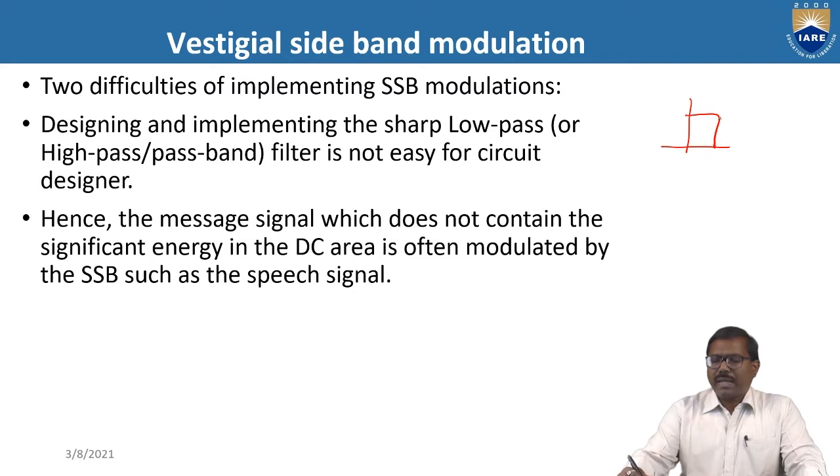So this sharp edge is difficult for the circuit designer to design. Another problem is that a message signal which does not contain significant energy in the DC area, such as the speech signal, is often modulated by SSB. So these two difficulties are overcome by this VSB, vestigial sideband.